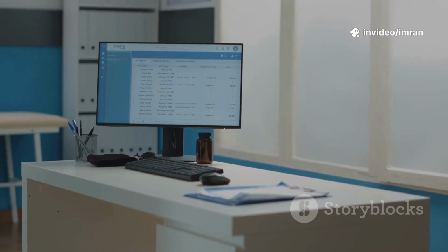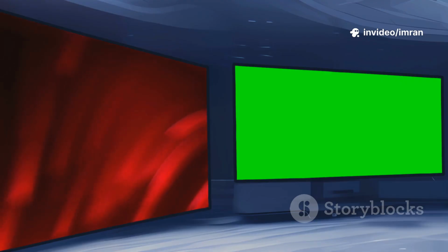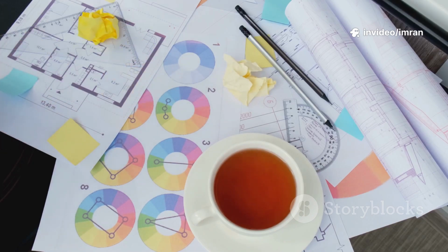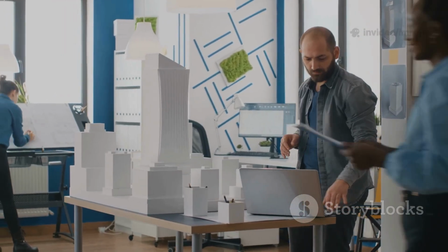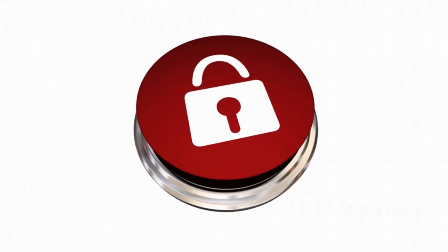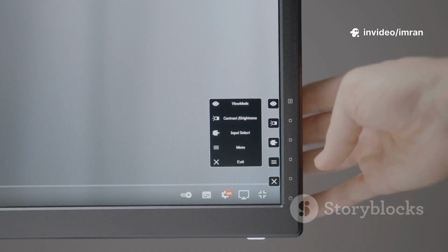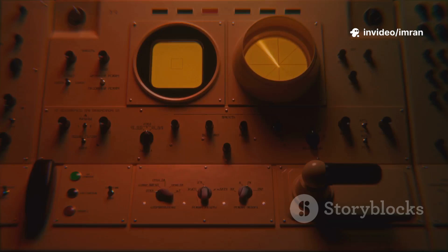The Layer Properties Manager is like a spreadsheet. Name your layers descriptively and use a consistent naming convention. Control visibility with on-off and freeze-thaw. Lock layers to prevent edits. Adjust color, line type, and line weight. Changes update instantly. This gives you incredible control.